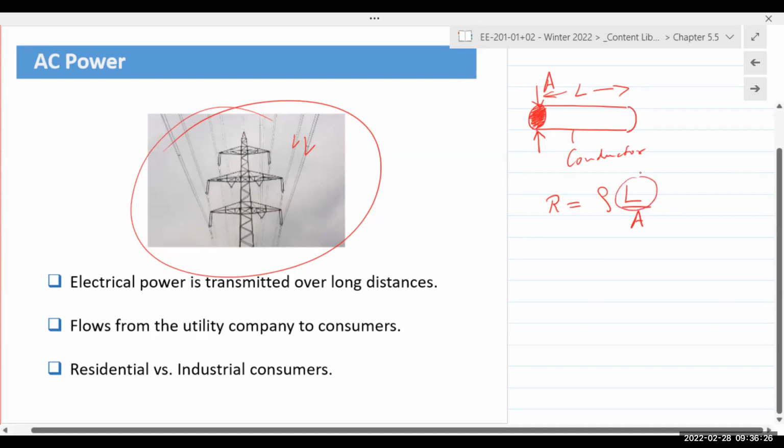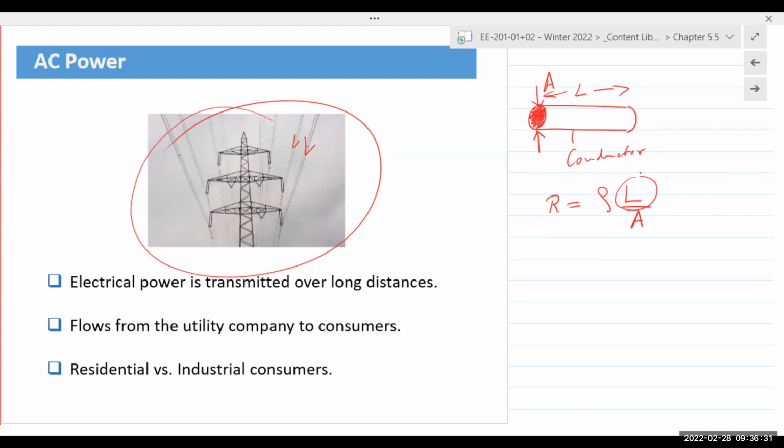typical wires and cables like these also have some resistance, but the length is very small: 3 feet, 10 feet, 25 feet, okay, very small. If you take, for instance, an HDMI cable running from a laptop to your TV, it's typically about 3 feet, 6 feet, at the most maybe 10 feet, not much more than that. That cable inherently has a resistance, inductance, and capacitance, okay? But the value of the resistance, inductance, and capacitance is not enough to disrupt the transmission of the signal.